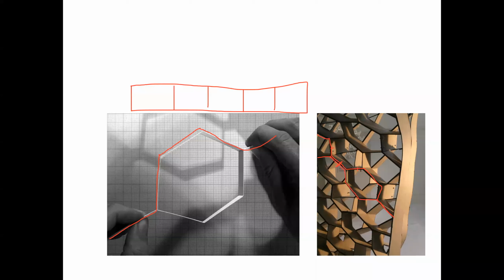And so if you can take a surface and begin to populate it with, in this case, hexagonal honeycomb, then you can begin to actually take each of these and lay them out, unroll them, or unfold them. And then you have a set of edges or lines for the laser cutter to score the material ever so slightly so you can fold it, and then a set of shapes around the outside for the through cuts to cut out each strip.